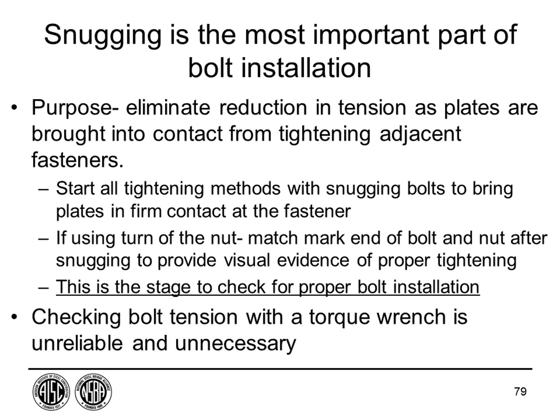One of the things I want to emphasize, because many times engineers are specifying the inspection, is that the most important thing in properly installing high-strength bolts in the large connections that we have in bridges is the snugging.